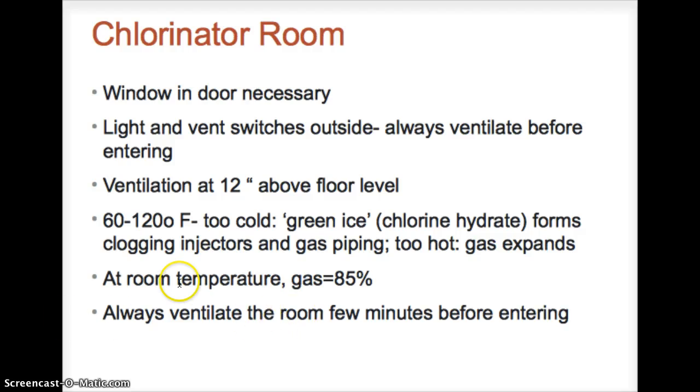At 60 to 120 degrees Fahrenheit is the proper range. When it's too cold for the room, green ice or chlorine hydrate forms, clogging injectors in the gas piping. When it's too hot, the gas can expand. At room temperature, gas is 85% in volume in the tank. And always ventilate the room before entering. Already said that.